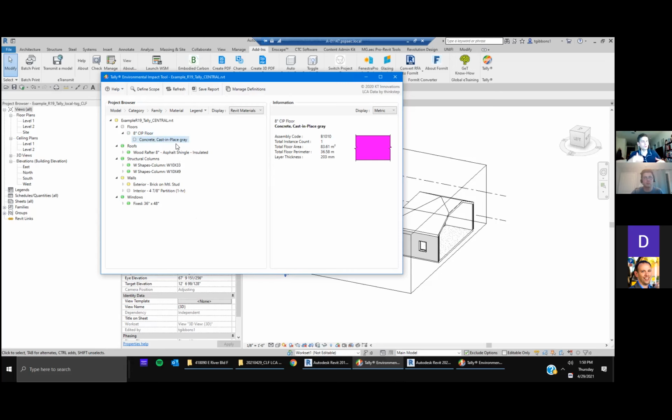And we'll get into this a little bit, but you can have a lot of different types of concrete in a project. So if the architectural model just has concrete everywhere, you then have to start to go in and select all the piles and say, these are 4,000 PSI concrete. And that's when I talk about detaching, whereas the slab might be 3,500 PSI concrete. So you might change that material in the model so that you can identify it through Tally more easily, so that your model has some more specificity in the materials that get mapped to Tally.